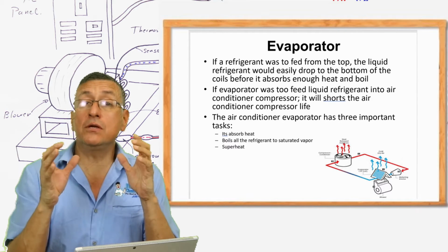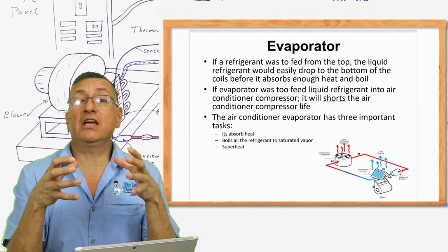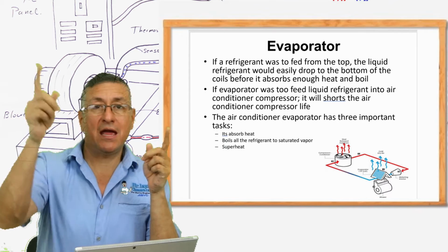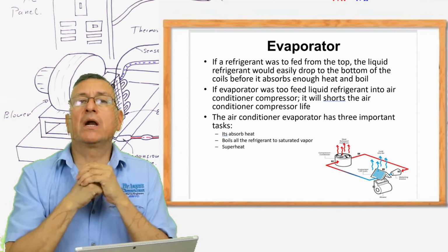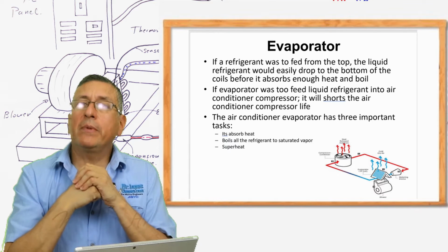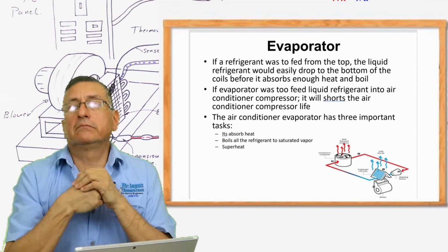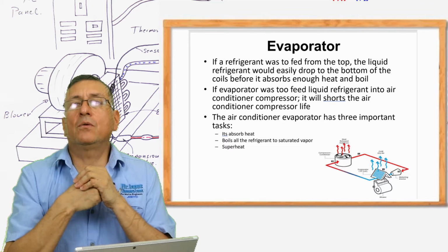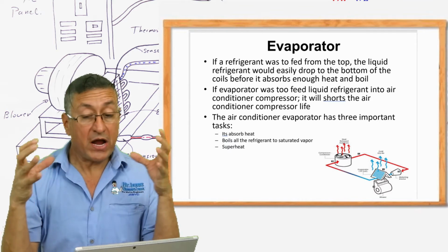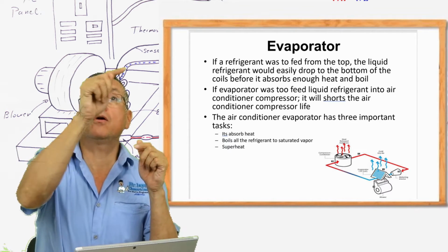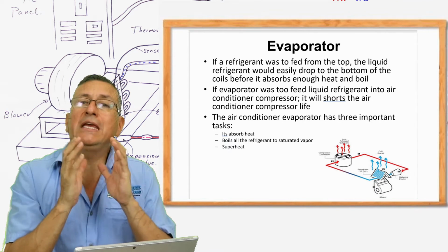If you are an engineer with the experience to calculate, according to the capacity of the compressor, how many evaporators you can connect, you are authorized. If not, I recommend calling an expert, the dealer specialized in air conditioning systems, and they will recommend the compressor according to the number of evaporators that you want to install. Yes, it's possible, but it should be calculated.